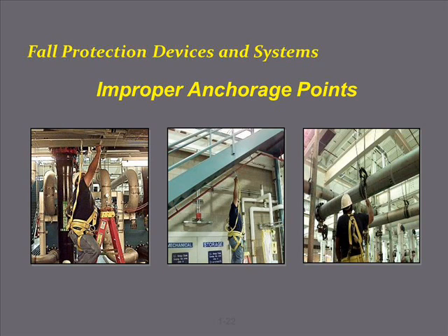Now here, let's look at some improper anchorage points. Remember, we don't ever want to tie off to live utilities. No pipes, ductwork, or conduits.